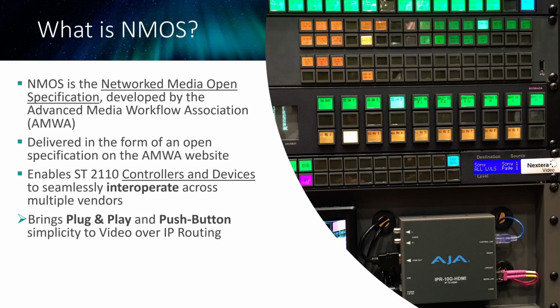Okay, so to begin with, what is NMOS? Well, it stands for Networked Media Open Specification, and it was developed by the AMWA, Advanced Media Workflow Association, and delivered in the format of this open specification to allow vendors to quickly adopt it and implement it in their products. What does it do? Well, it enables control of ST2110 devices, and it enables them to seamlessly interoperate.